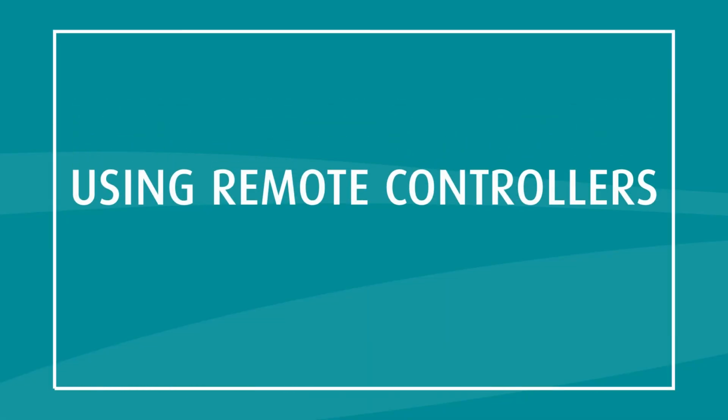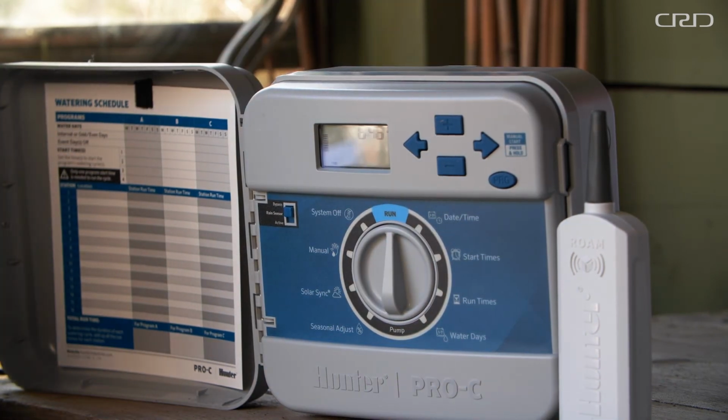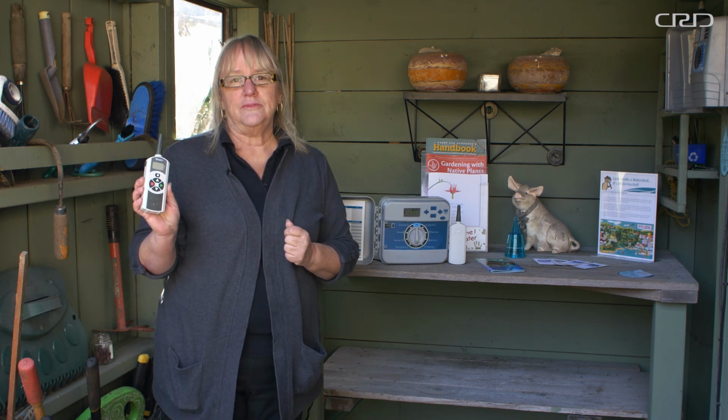Other equipment that's available for irrigation systems are remote controllers. A remote will have a communication device that goes from your controller to a handheld device. Where this becomes most useful and most effective in water savings is if I'm doing maintenance. I can turn my sprinklers on and off from a handheld remote, very similar to what a TV remote is. And now my sprinklers aren't running as long. So if I'm doing maintenance or I'm working in the garden, I don't have to run back to my controller to turn things on and off.